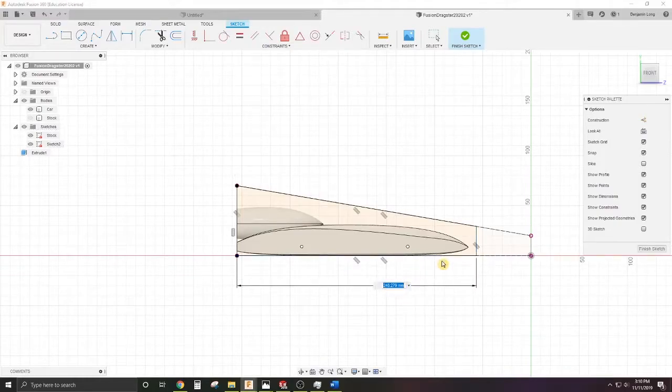And how do we know what this value is going to be? We are going to leave an actual exclusion zone here. Okay, and you can see here that exclusion zone is going to be like this. We're going to leave 15 millimeters that we're not going to cut here at the front of the car. And we're going to leave that so that the block can stay attached in the mill in the fixture so it's held in place.